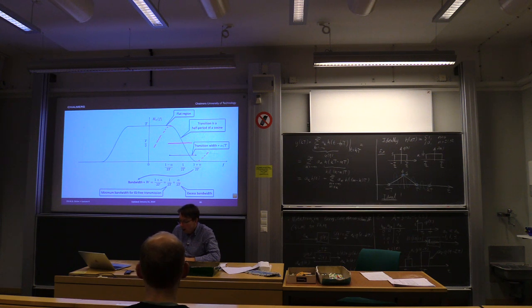Okay, and the bandwidth of this is determined by this factor. So the bandwidth depends on a parameter alpha. And alpha we can choose between 0 and 1. Okay, it's a design choice. Then one can see that the bandwidth here, W, is (1 plus alpha) over 2T.